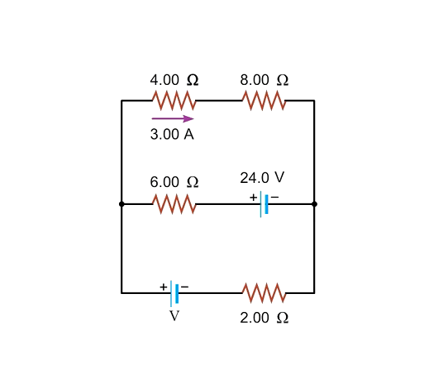Let us begin with step 1 of the problem-solving strategy, drawing the directions of the currents in the top and bottom loops. Remember, our choice is just a guess. If we pick the wrong direction, we will end up with negative currents for the answers. We will start by drawing the current through the 6-ohm resistor as moving to the right. We will also place plus and minus signs on the ends of the resistor to show the higher electrical potential and lower electrical potential ends.